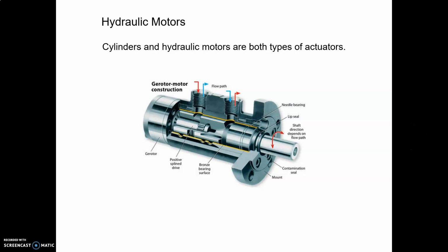We are still thinking about round things that rotate, and we just looked at pumps. Now we'll think about hydraulic motors, but we are moving on to a different place in the hydraulic circuit. We are now thinking about actuators. An actuator is something that does some work for you: grabbing, pushing, rotating, moving. A cylinder is a kind of actuator, and a cylinder, which we'll look at next week, converts oil pressure to linear motion. A hydraulic motor converts oil pressure to rotary motion.